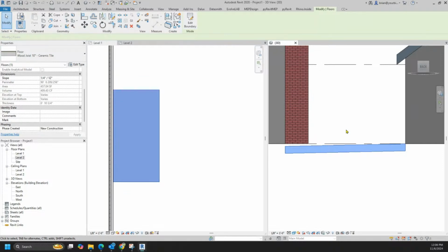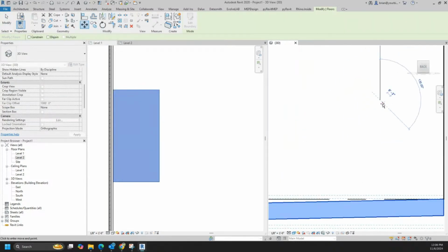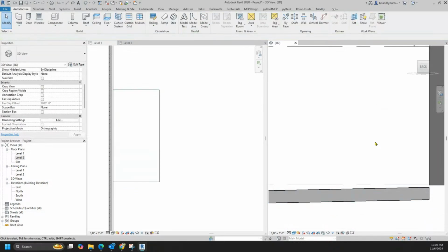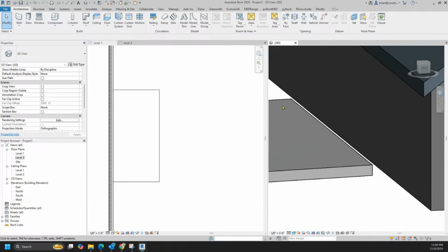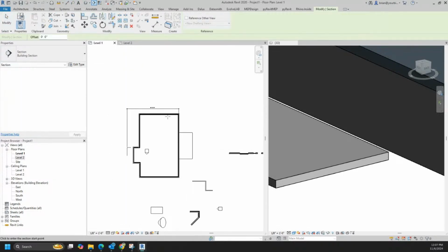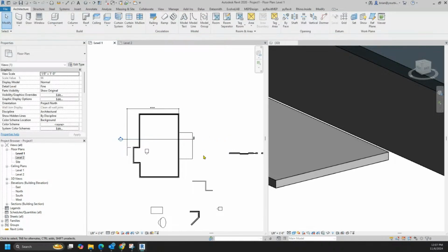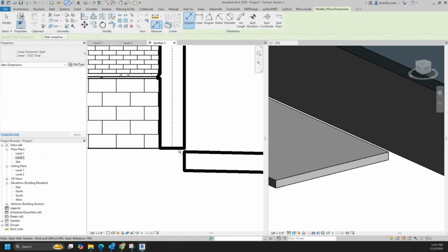What's more important to me is if I tell you it's down 2 inches, can you make it go down 2 inches? So you see, I just put it right at 0. Mm-hmm. If Brian's telling me it needs to be down 2 inches, I just go here and I would go 1, 2. I'm not zoomed in far enough. 1, 2. Now I know I'm exactly down 2 inches. So that at some point later down the line, when I have to put a dimension in there, which of course you're going to find out, you can't put a dimension in a 3D view, but you could in a section. We could end up coming back in a week or two when we're setting up our drawings, cut our beautiful section here, and find out that, yes, indeed, Brian had that exactly at 2 inches.